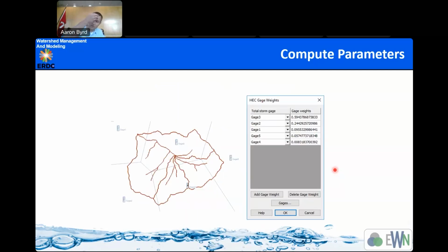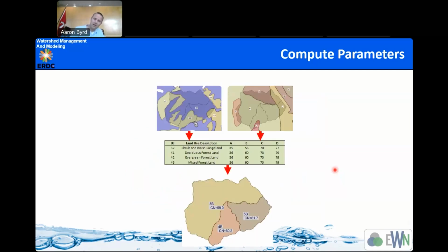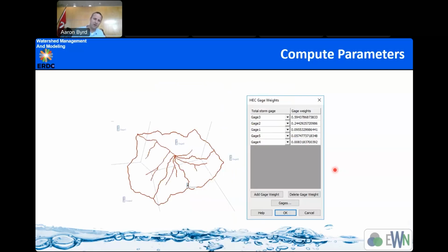But what we'll do is we go through the GSSHA course. It also helps you compute rainfall, but as we go through the GSSHA course, we're going to use some of these tools that are used to compute the curve number to define what we call an index map. We're going to be talking about this later, but you'll define something called an index map where you define different land use areas in your watershed and/or different soil type areas and define parameters for each of those areas.